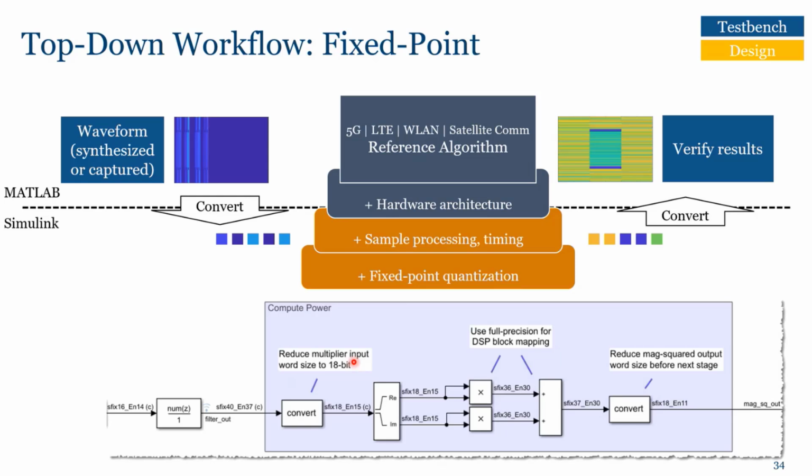or on a block level. You can also add some pragmas that are added later on in the code, where you can ask the synthesis tool to map, for example, this multiplier on DSPs. We can also manually change the output data type, or the input or output data type for your subsystem. So you can limit the data types on the input and the output of your subsystem using these convert blocks.